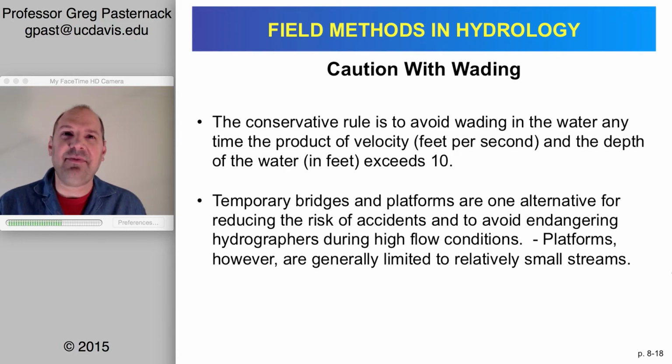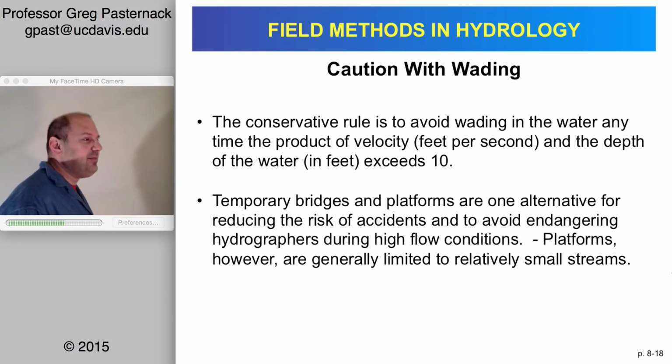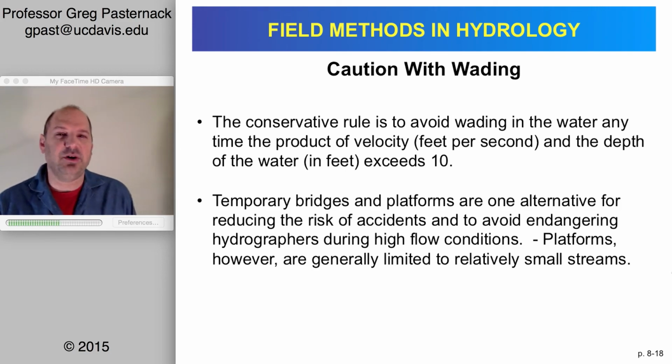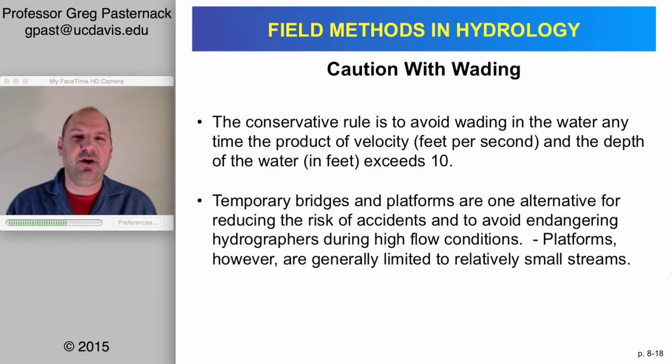So remember that as depth increases, the force on you is based on the projected area. So staying in a perpendicular streamlined position so that the flow is hitting a smaller projected area is helpful. But force is proportional to velocity squared. So going from 2 foot depth to 3 foot depth is not as big a deal as going from 2 feet per second to 3 feet per second. Also, once you get chest deep in water, I've experienced a kind of buoyancy effect where you just start wanting to float, unless you have weights holding you down. It's not just a question of direct force, but there's also that buoyancy force that your body's experiencing that you don't feel when you're only 2 feet down.